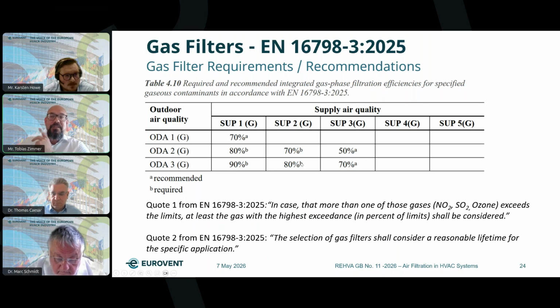What the standard does not tell you is whether it's an LD, MD, or HD 80. But what's obvious is the lower your filter class, an LD needs to be changed more often than an MD, which needs to be changed more often than an HD. And there are two additional comments in the standard explaining how to select it.